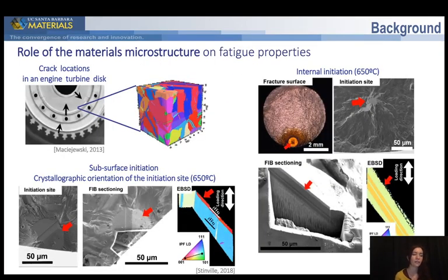When analyzing the location of fatal cracks in fatigued specimens, it was found that both bulk and surface initiation sites are often associated with specific boundaries between crystals, which are called twin boundaries. And yet, not all twin boundaries are crack initiation sites, and there is still a lack of understanding on where and why cracks would nucleate in particular areas of the microstructure. The observation of cracks in these particular microstructure regions suggests that there were regions where stresses were previously concentrated.